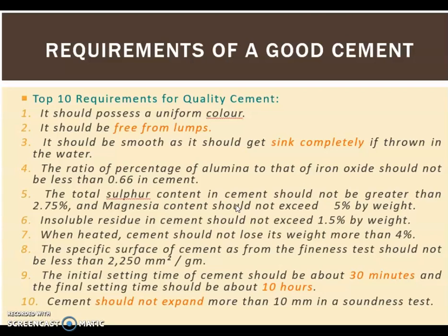Okay. Initial setting time should be about 30 minutes and final should be about 10 hours. Cement should not expand more than 10 mm in the soundness test. Now, what is this soundness test? Okay, I'll just show you what the soundness test is.